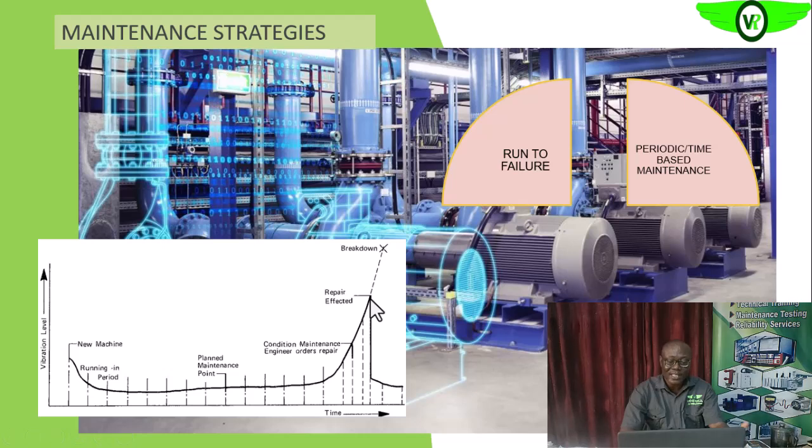As the insulation of the electrical equipment is entering this wear out region, we re-insulate. All of this is to bring the condition back to normal, that is, to improve the condition of the component or the equipment. So that is what the preventive maintenance program is based on.